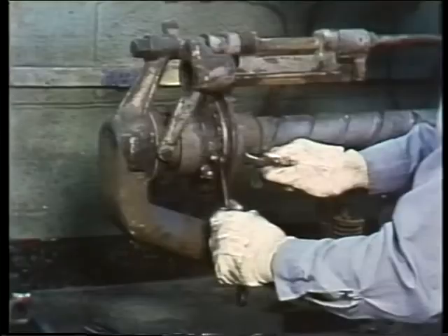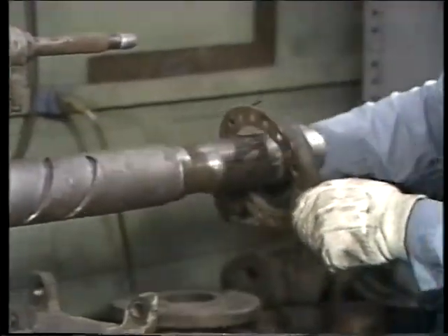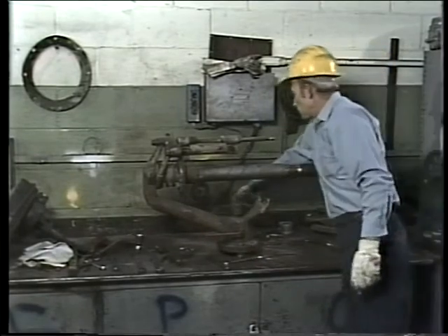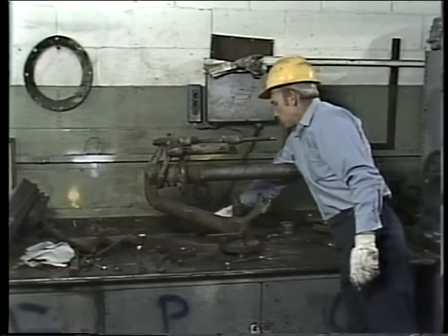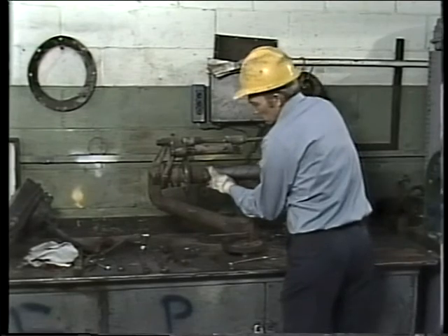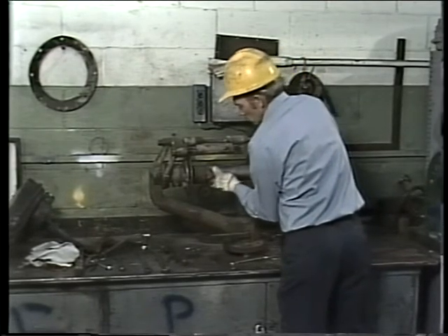On this particular soot blower, the cam may be removed from the element at this point. When the retaining bolts are removed, the cam can also be pulled off over the head of the element. The element is free to slide off the end of the feed tube.